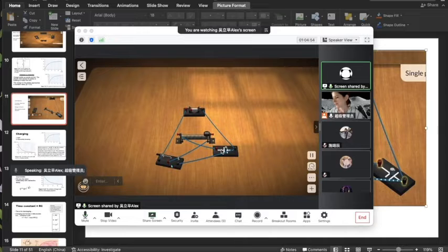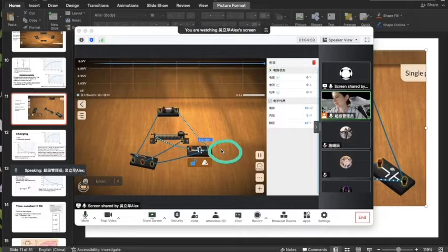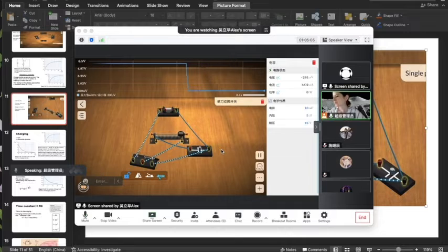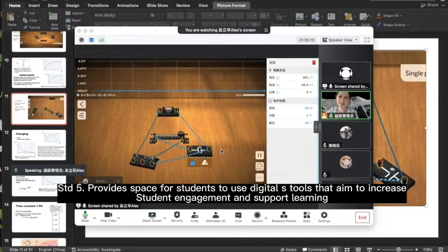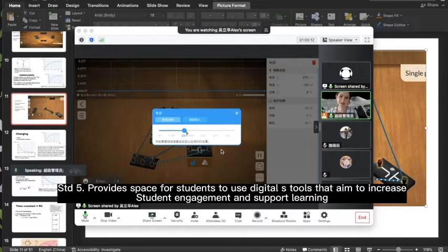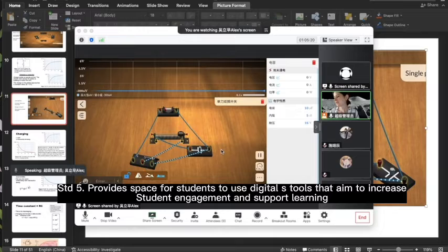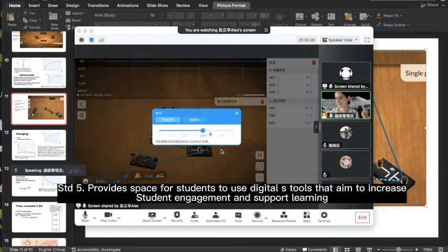Okay, so let's go back and look at the voltage of the capacitor. Let's see it charge up and discharge again. See how fast it is. Okay, increase. Still fast. Let's try to change C again, but not quite so big. One is very, very big. Maybe like, yeah, that one. 10 microfarads. Like this one? Yeah. Try maybe 100 now. Okay, 100 microfarads.